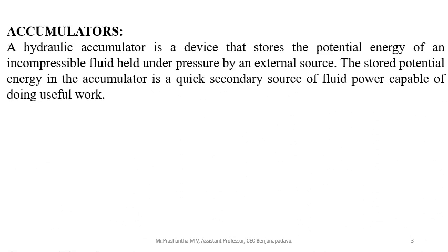Accumulator is a device used for storing the pressure energy of the liquid. A hydraulic accumulator stores the potential energy or pressure energy of an incompressible fluid held under pressure by an external source. The stored potential energy in the accumulator is a quick secondary source of fluid power capable of doing useful work.